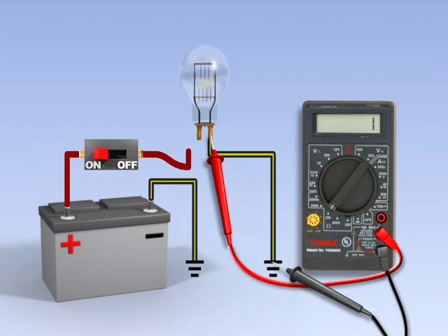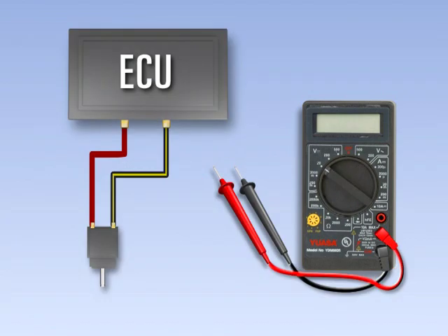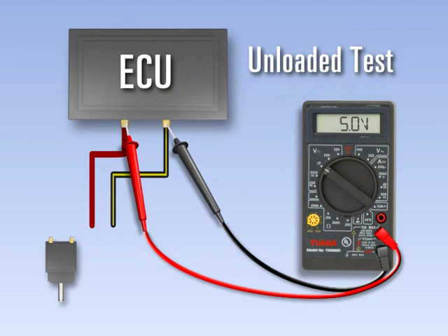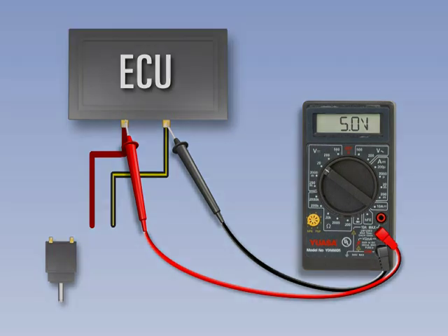It's important to note that on some circuits there are 2 voltage tests, loaded and unloaded. During a loaded test, a component is left connected to the circuit, while in the unloaded test, the component is disconnected. Always consult the vehicle's service manual and perform both tests if required.